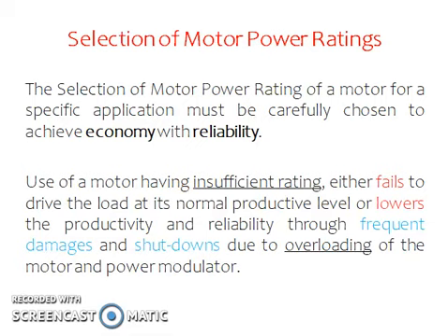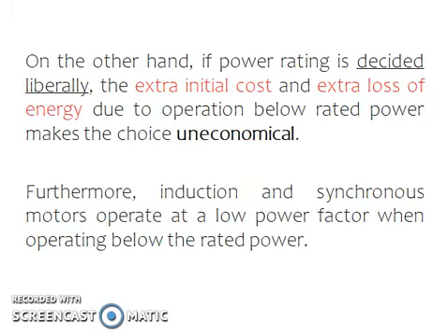On the other hand, if the power rating is decided very liberally, then the extra initial cost and extra loss of energy due to the operation below rated power make the choice very uneconomical. Further, induction motors and synchronous motors, these two operate at a very low power factor when operating below rated power.